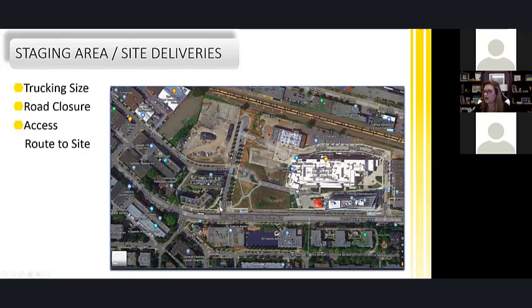And what we found now is that the panels we want to bring in for this particular project, we had anticipated would come in here, but they can't make this corner. This is a very, very busy street. And now how do you get these panels in here? And there's another very busy street on the other side, and turning these large trucks around. So these are the types of things that we're required to think about. By reducing our panel sizes by about 4 feet, we actually can make the corner by driving up onto the city sidewalk and coming in.